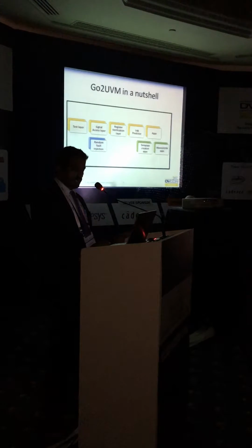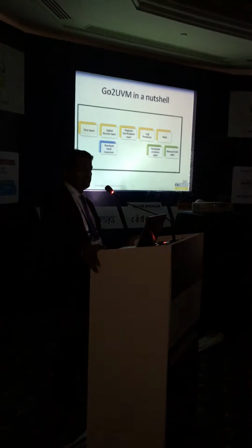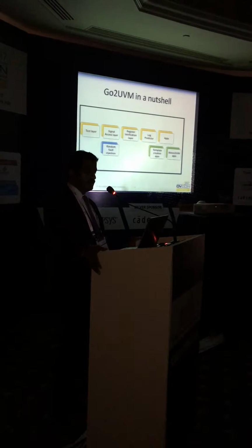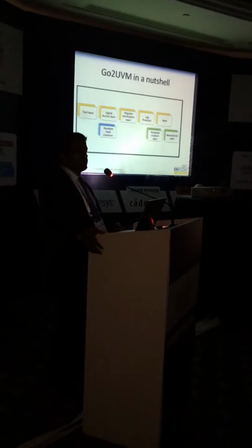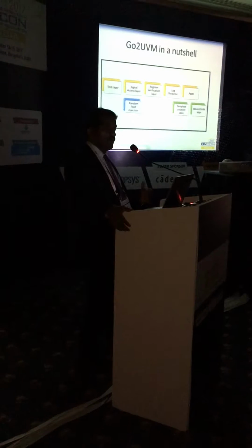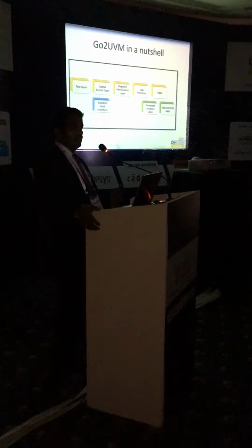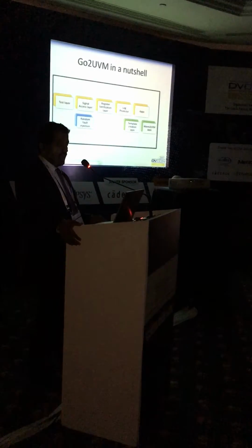And there is a log predictor as well. For those familiar with the full UVM picture, this is a UVM RAL and this is a UVM reg_predictor. This is modeled along the same lines, saying, if I can predict the register contents, how about trying to predict my log file? Again, these are required in functional safety requirements and so on. That's where this is very applicable. And there are some of the apps, like the template creation app and the Waves to UVM app, which I've introduced today.